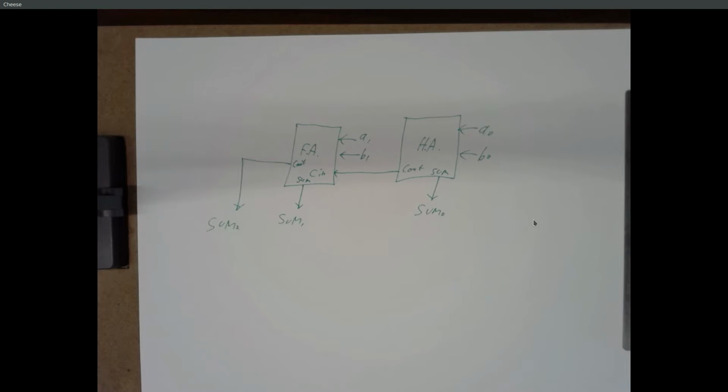All right, that's a lot of stuff. Questions about that? So a half adder is just a full adder but without a carry in? Exactly. A half adder is just a full adder without a carry in, or specifically where you think the carry in is always 0. So it still does A plus B plus a carry in, with carry in 0. So it just does A plus B.